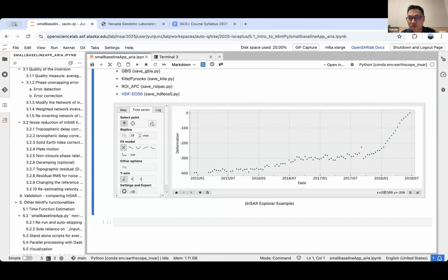And so in the code, by default it is assuming there's no north-south deformation. So if you know there is no north-south deformation, then you do that decomposition, you can get the right east-west component. Otherwise, the estimation is biased, as you can imagine.